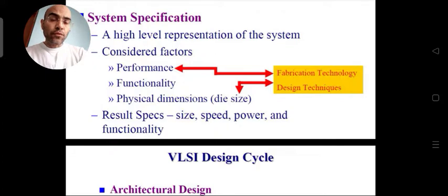Nowadays, people are working on 11 nanometer technology, or 7 nanometer technology. So what does it mean? It means the length of the gate, or the distance between the source and the drain region of your MOSFET, is 11 nanometers or 7 nanometers. So whatever is the feature size or the technology size of your devices, or the technology in which you are working, it is this number.